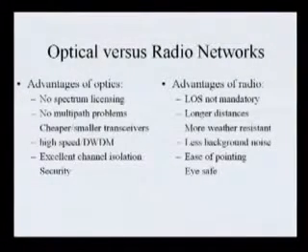So we actually look at the two technologies, and we're doing both, both the laser links and also the radio link. But when it comes to radio link, you need to worry about the spectrum available. So we've chosen one frequency band at 57 to 64 gigahertz, and that's extremely high frequency. Your 802.11 here is 2.4 gigahertz, so you're talking about 30 times higher.